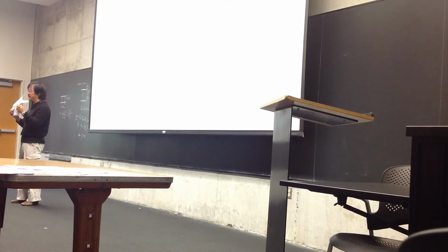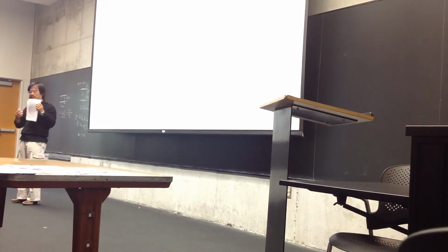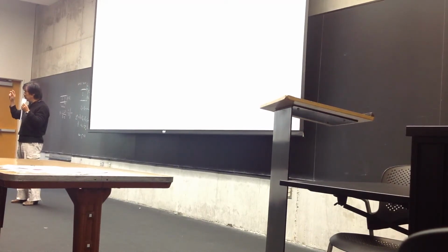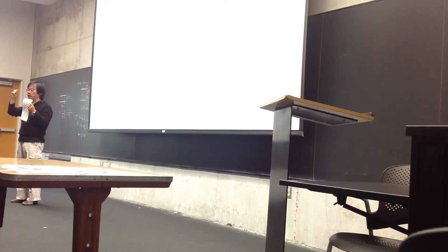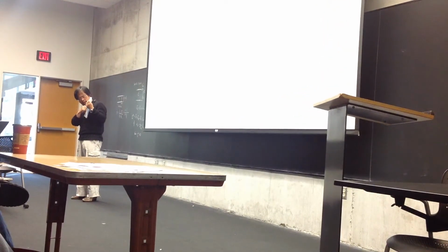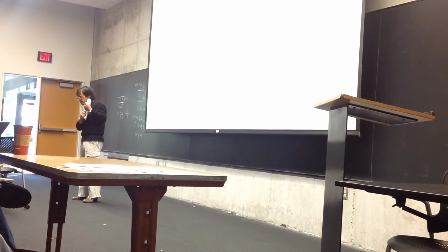You may want to become a best friend with a Smith chart, at least in the next few lectures. So the first thing you do, for a problem which we are going to show, is identify the impedance, and then normalize that impedance with respect to Z0. So you got a real part, you got an imaginary part. You go to the Smith chart. You see all those circles here. This is a big circle corresponding to R equal to 0, and here's R equal to this and this. And also this is a circle which is passing through the origin, which is the R equal to 1 circle.